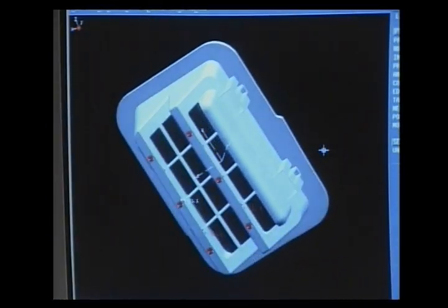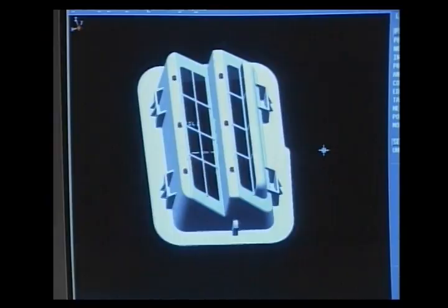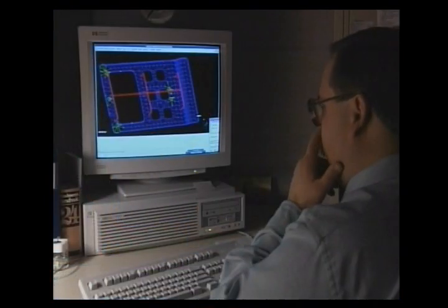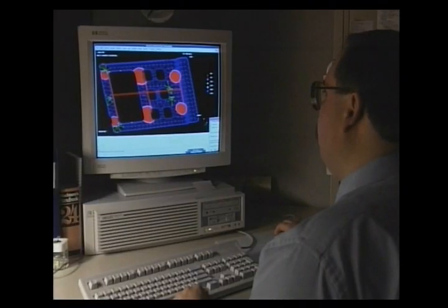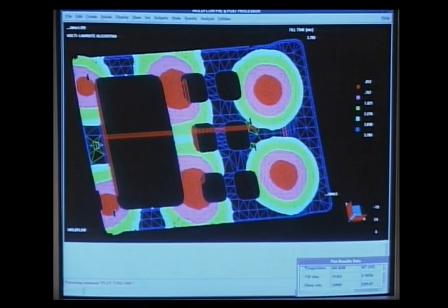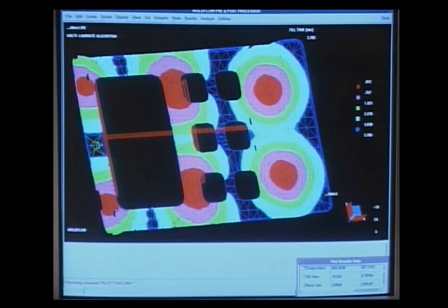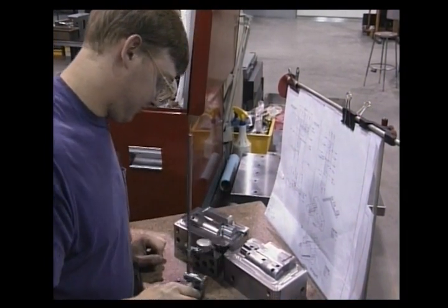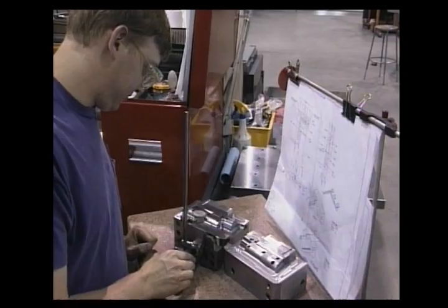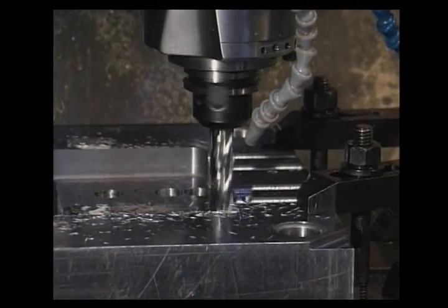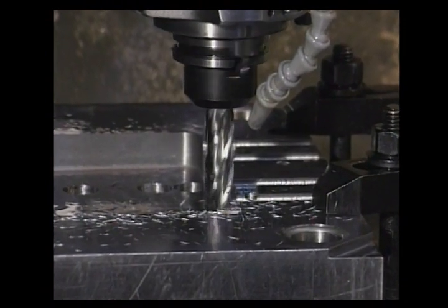Additionally, computers are used for various activities throughout the design and construction of the injection mold. Computer software packages can approximate and visualize various conditions within the injection mold, providing valuable feedback for the part and mold design. These packages can also convert designs into mold drawings and provide programming data for automatic machining of the mold base, cavities, and cores.